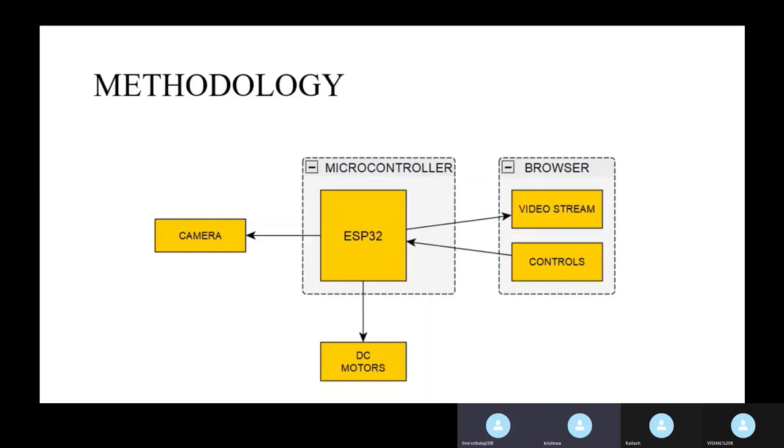The methodology of the project is, first, we are using an ESP32 49-pin microcontroller. With that, we are connecting DC motors by using a motor driver and a camera, and all those controls will be controlled through a browser where the whole console will be there, including video streams.